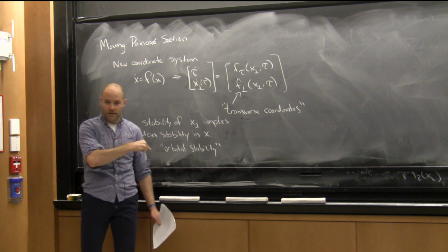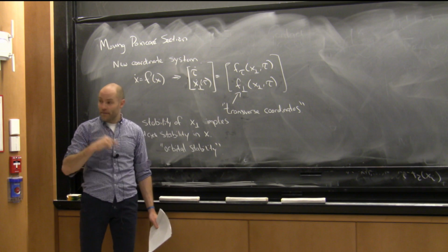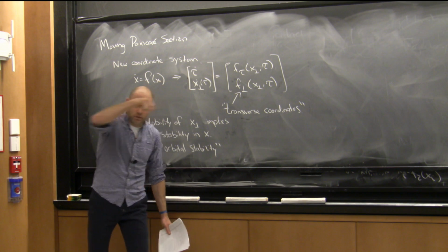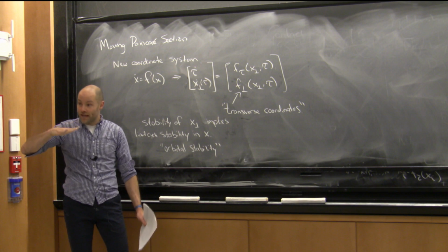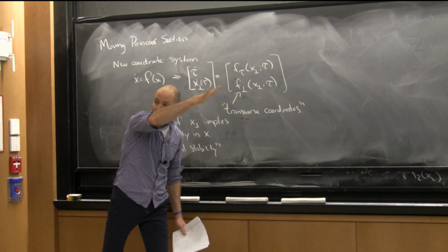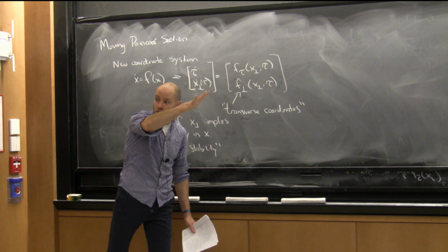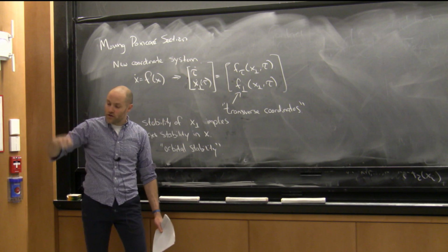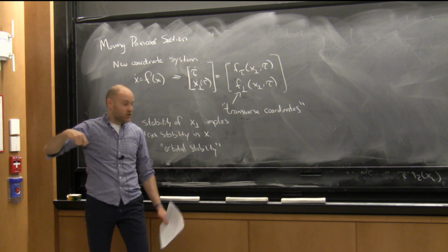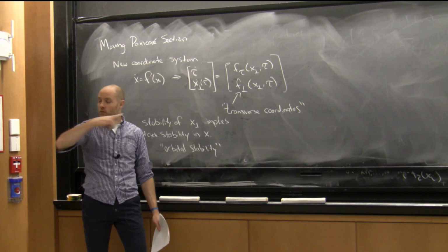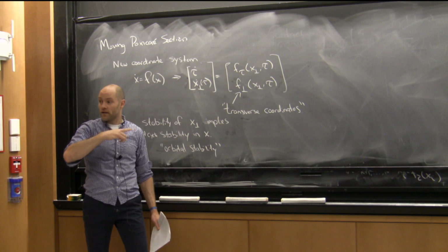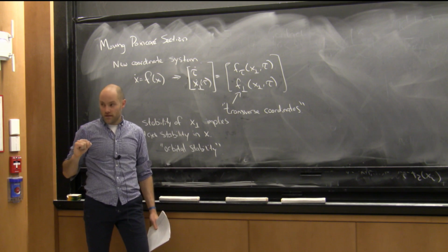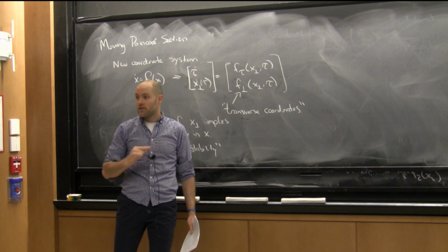You asked a question back when we were doing LQR, for instance, the time-varying linearization, right? That if I took my perching plane, grabbed it in the air, and pulled it back, the stabilization we wrote would try to catch up with the initial trajectory. That's the only way it knew how to do it in that solution. If we wanted our perching plane to not care where it was on the solution, but just look for the closest point on the original trajectory, searching over tau, then we could use this tool to do that, even though that's a finite duration trajectory. Okay? We're going to talk about the stabilization at the end, so let's come back to that.